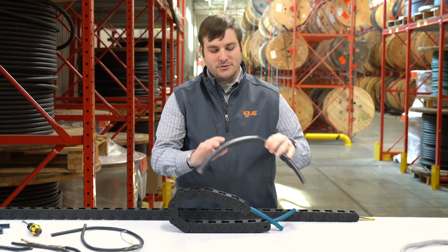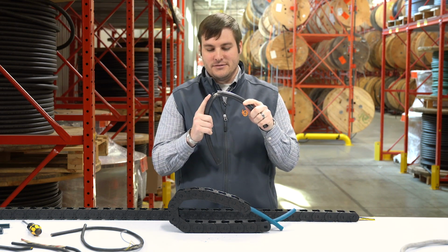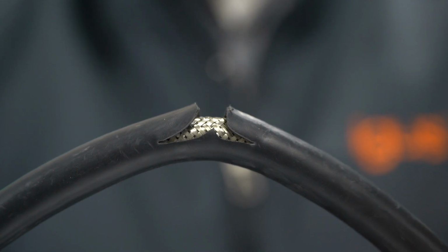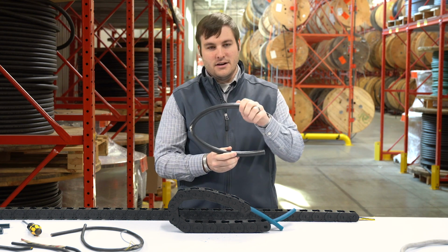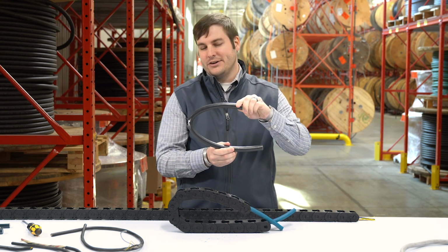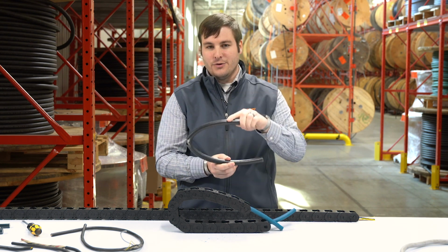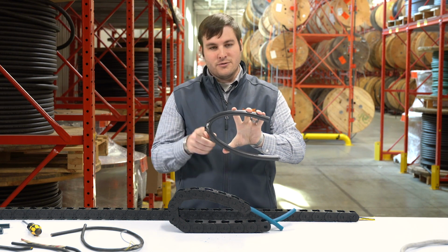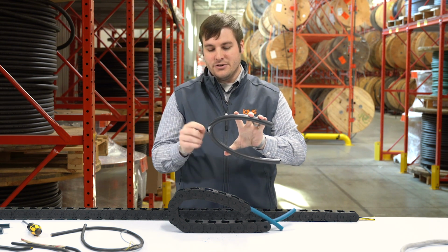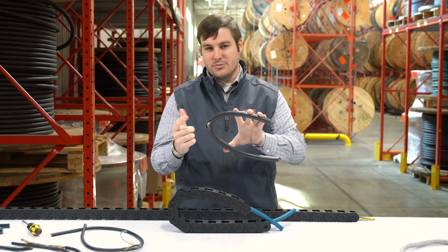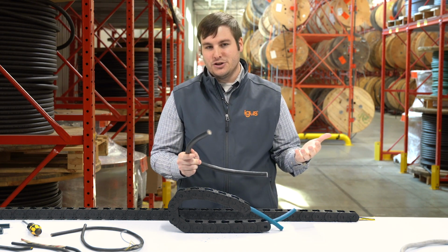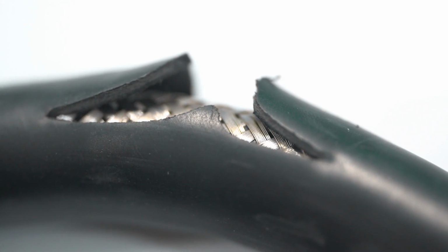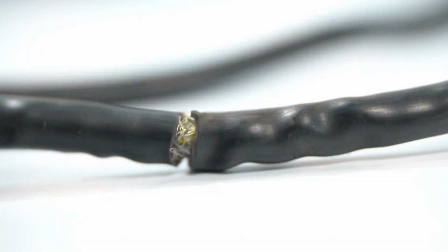Here we have an example of a cable that has a cracked jacket. Now, why does cracking happen? Typically because of two reasons. One, the bend radius of the cable inside of a cable carrier, or E-chain, is too low, and therefore there's mechanical forces acting on the jacket material that are forcing it to essentially break apart. The second reason could be a temperature issue for a material that particular cable isn't resistant to.